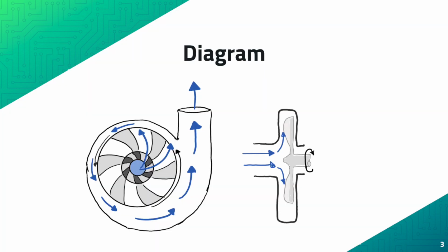The centrifugal pump, which is driven by the two-stroke engine, creates the airflow to blow away leaves and debris. Air enters the system at the low-pressure region at the center of the pump. As the impeller blades rotate counterclockwise, the fluid is accelerated towards the outside of the volute as demonstrated in the diagram. The fluid then travels from the narrower to wider region within the volute casing, effectively exchanging velocity for pressure, causing a larger pressure difference.